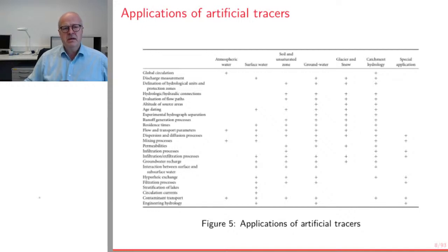So 3 candidates. What you do is visit the place, inspect the place, and add 3 different tracers, one to each of the potential sources. You inject, you wait, you measure in the spring until you detect something. Then first of all, you know where the pollution comes from, whether it's from the farm, the street, or the waste dump. And you can also detect when the tracer arrives and how much, the breakthrough curve, so you actually learn about this hydraulic connection.